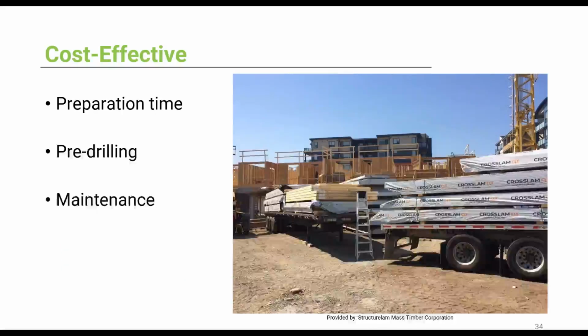To lift the panel, there's always some preparation time with all of these devices. For most devices, including some in the screw hoist system that we just saw, you need to pre-drill the right diameter hole in the correct spot before installing the rigging device. And you need to maintain these systems all the time to make sure that they're not damaged. But believe it or not, you need to make sure that the pre-drilled holes are actually free from things like sawdust and other things that can get stuck in them. And most importantly, there's a cost associated with all of this, especially with the installation labor.